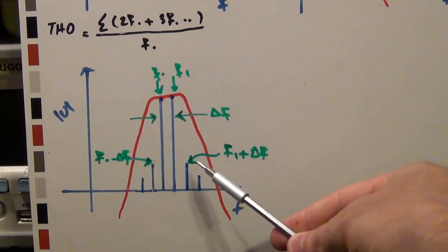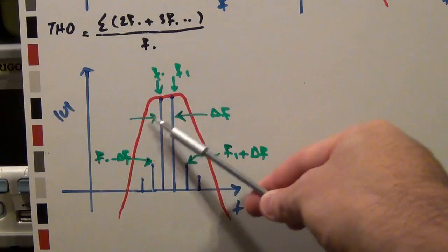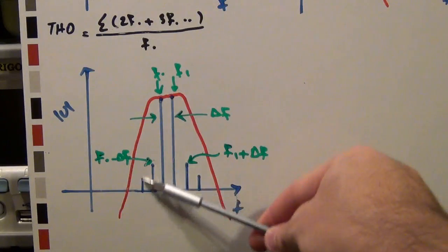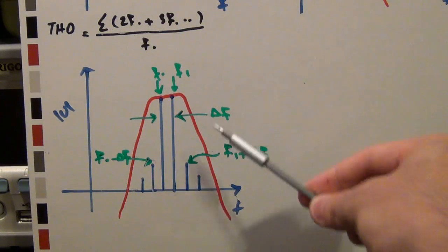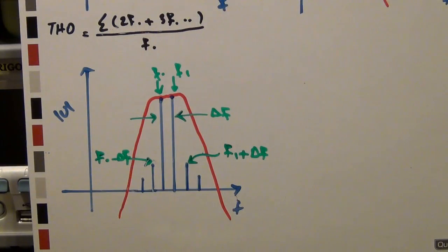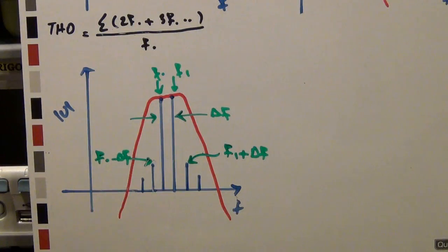So then the receiver is going to be confused. It doesn't know if it's listening to your harmonics or if it's listening to the signal the actual user is sending. So if you don't meet the requirements and make sure that your harmonics, your nonlinearity, is low enough, your circuit's not going to pass the mask, may not pass the FCC, and you wouldn't be able to put it into the market. So this is a very, very important test. And then people measure how fast these grow and then where they meet. I recommend that you go and read that because it becomes a little more technical and it would be very boring for me to go through it.